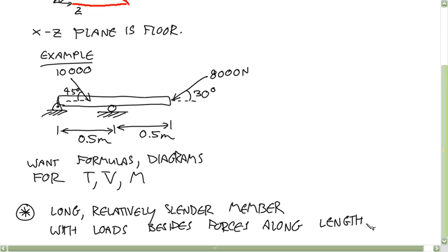Okay, so what this means is when you do truss problems and you neglect the weight of the members, remember then those are two force bodies and all you have are forces acting from one joint toward the other joint, okay? Then those aren't beams, even if those members are made by an I-beam company. Those aren't beams the way we talk about beams. In order for something to be a beam, you need a third force, or you need a couple. You need some kind of lateral load or a couple.